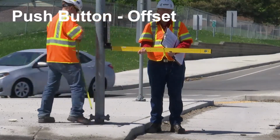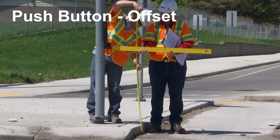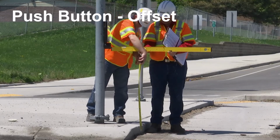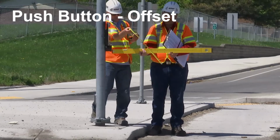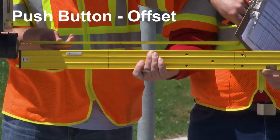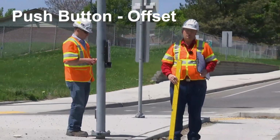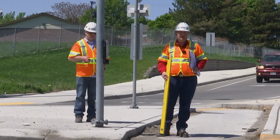Next, we want to measure how far away we are from the turning space. So we put our level up to the push button, and we can put our tape measure straight down. And we put a little mark there on the smart level to see where we hit. So right there. And then we can measure how far that is. 15 inches. And we're at 15 inches. So once again, we're over our 10 inches, but we're under our 18. So if we got engineer approval, then we could be compliant within that 18 inches.